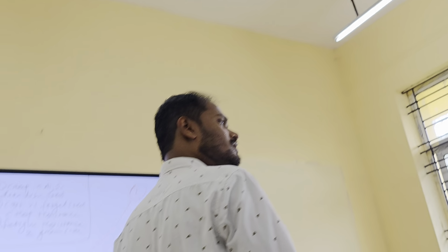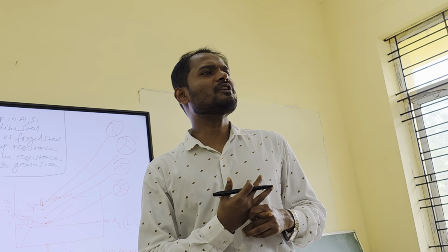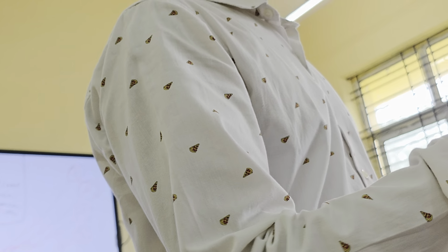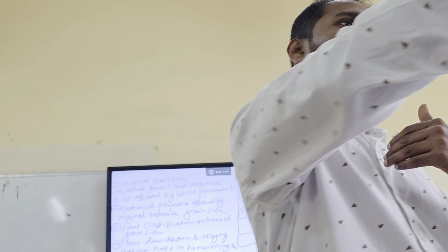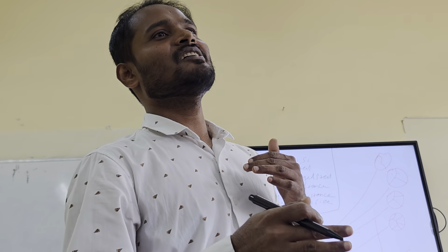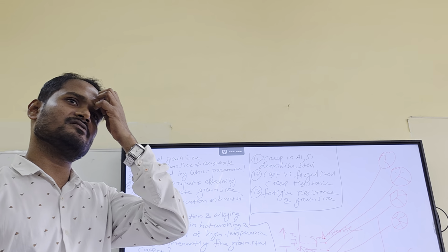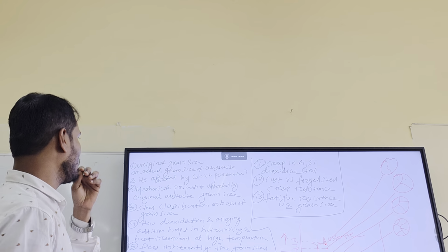So where there is impact, when sudden loading is there, in that condition you need high toughness. Maybe your HOD sir is teaching you testing of materials, and you are going to do one experiment downstairs. We have an impact tester, the Charpy impact tester. A load will hit the specimen at a very high velocity. If toughness is good, it will just bend. But if toughness is poor, it will break. Actually, we want to break it to see the morphology and how much energy it is absorbing. Anyways, fine.